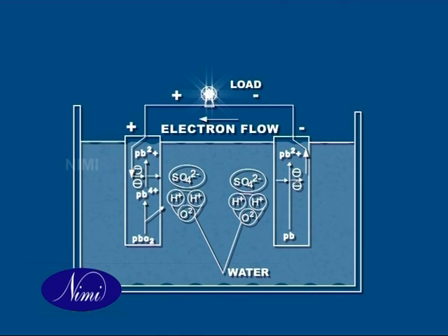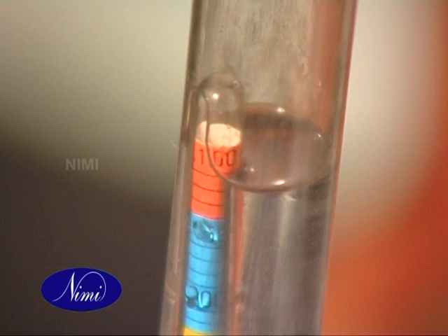Since both the plates approach the same material chemically, the potential difference between the plates begins to decrease. At the same time, the combining of oxygen in the lead peroxide with the hydrogen atoms of the electrolyte forms water. When the battery discharges, the sulfuric acid becomes weaker with its specific gravity approaching 1.0.